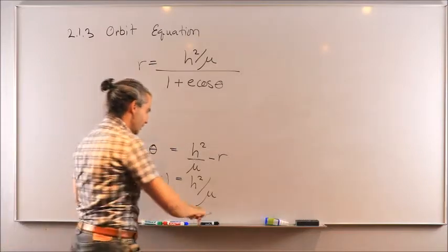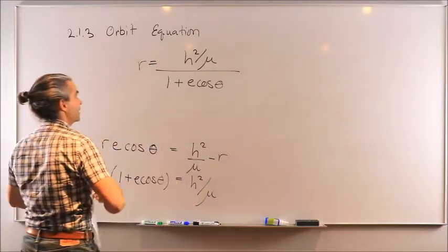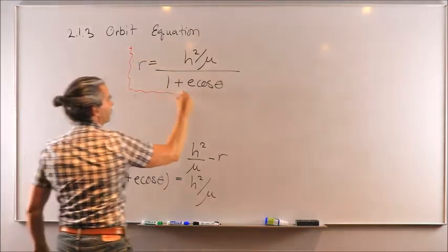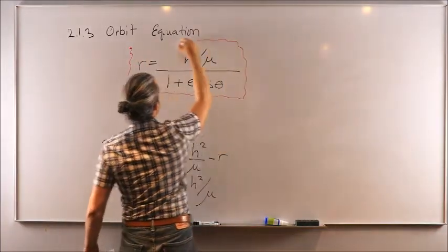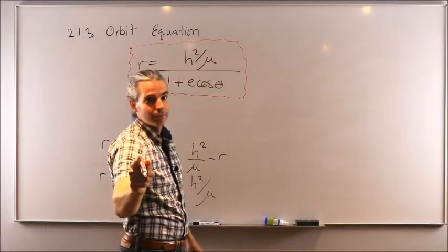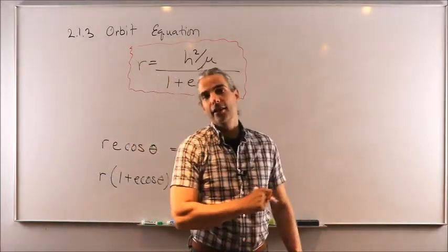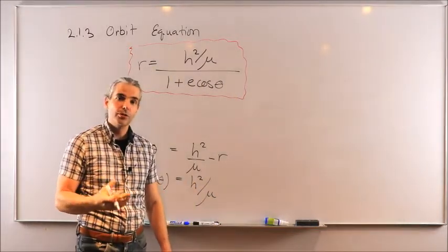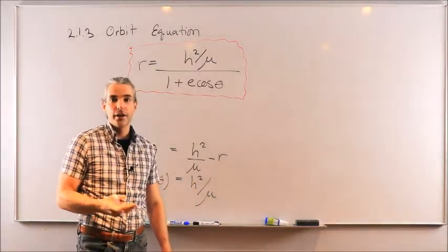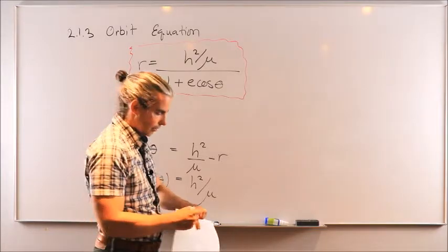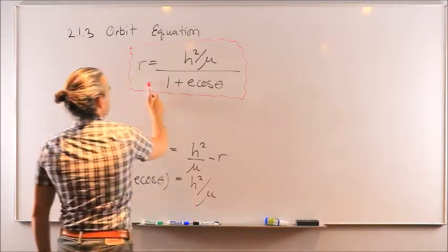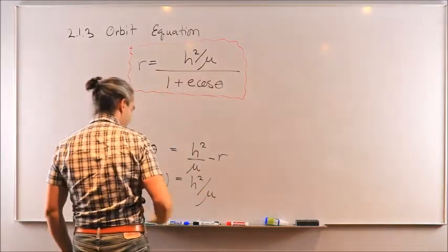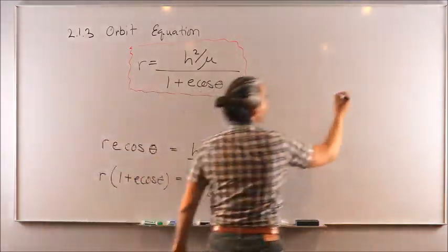Yes, well done. That is great because this is, again, the second most powerful equation in this course after the two-body equation of motion, which was equal to, yes, exactly, r vector double dot is equal to minus mu over r cubed times the r vector, okay? So this is great because now it allows us to solve for the distance between m2 and m1.